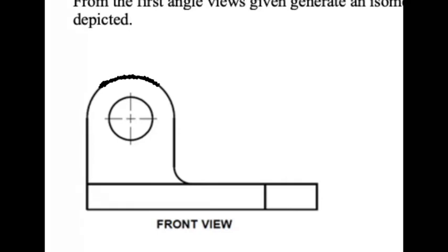Now in our next example, we start to see the benefits of understanding first and third angle projections. The example is, if you were given a single view of an object, such as the one over here, from it you certainly cannot draw the object or visualize the object, should I say. Especially this bit sticking up. Is it the full width of the whole object? Is it less? Is it positioned at the back of the object? Is it positioned at the front of the object? It's hard to know. This hard line here might well indicate a cut-off corner, but we don't know enough about it.